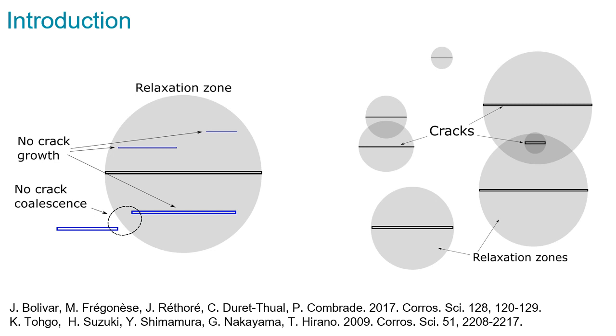Usually, for modeling the second stage of stress corrosion cracking, large colonies of parallel cracks perpendicular to the applied tensile load are considered. The interaction between multiple cracks may significantly alter the stress concentration in the vicinity of crack tips. Depending on the configuration of the crack array, it can either increase or decrease stress intensity factors. Here we'll study the second effect.